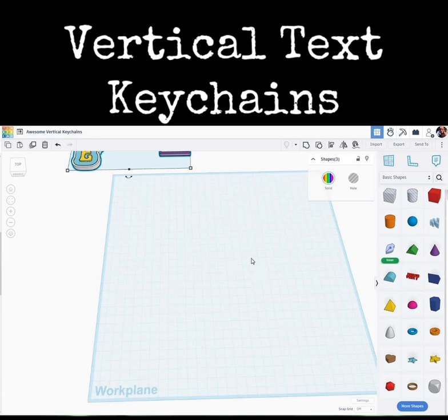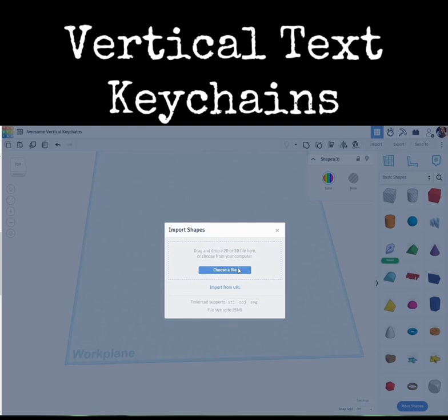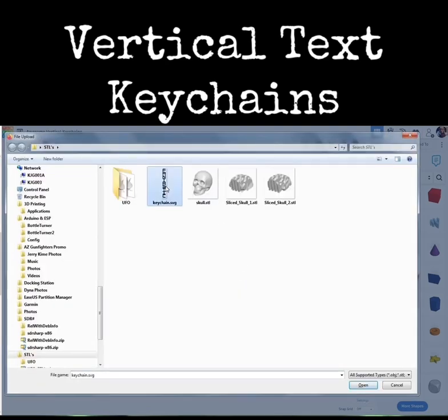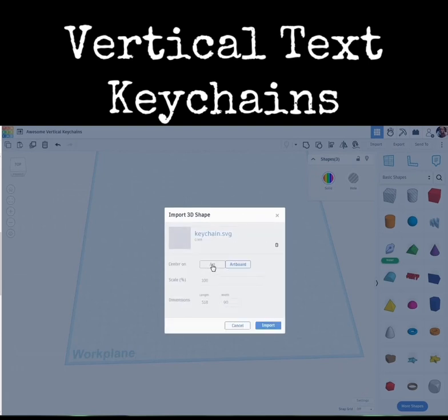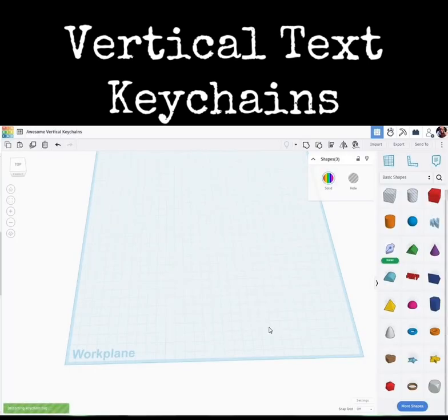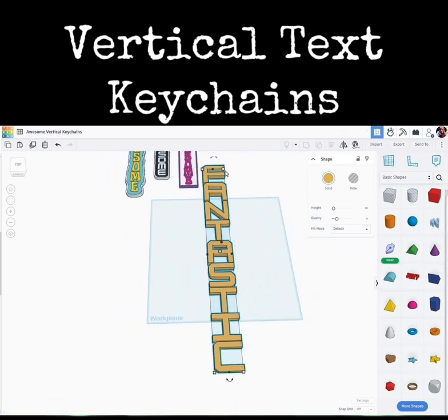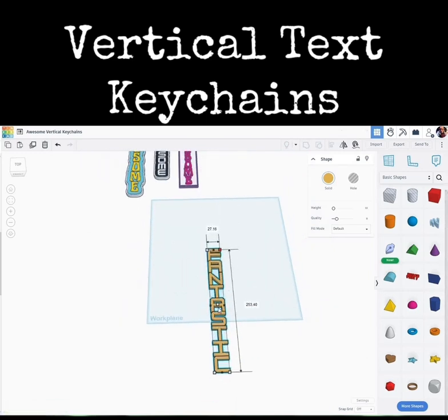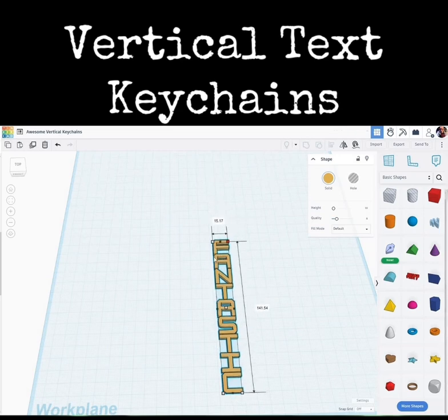Now let's come back to TinkerCAD. Let's come here and let's do Import. Choose from File. There's our SVG, and let's click on that. All right, let's click on Art instead of Artboard. We want to make this Art. We'll say Import. Once it's imported, we may need to alter the size here a bit. Let's shrink that up. Zoom back in here. There's something a little more reasonable.